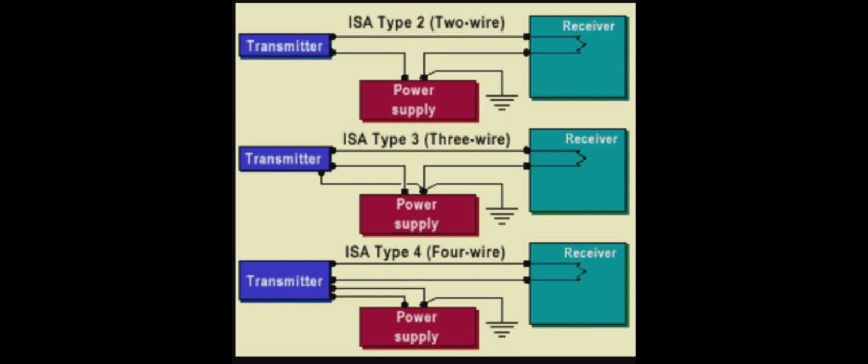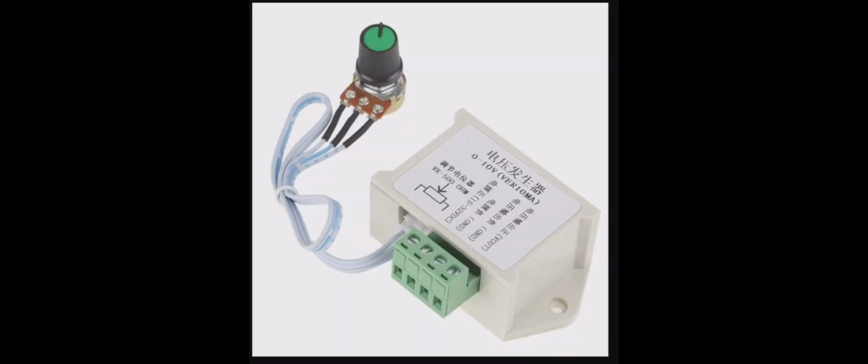It is not only 4 to 20 milliampere. Some devices operate on 0 to 10 volt DC as well, or 1 to 5 volt DC. So DC voltage outputs are also commonly used as a universal signal for process control. As we go into detail in instrumentation or process industries, we will come to know that 0 to 10 volt is also used for analog.